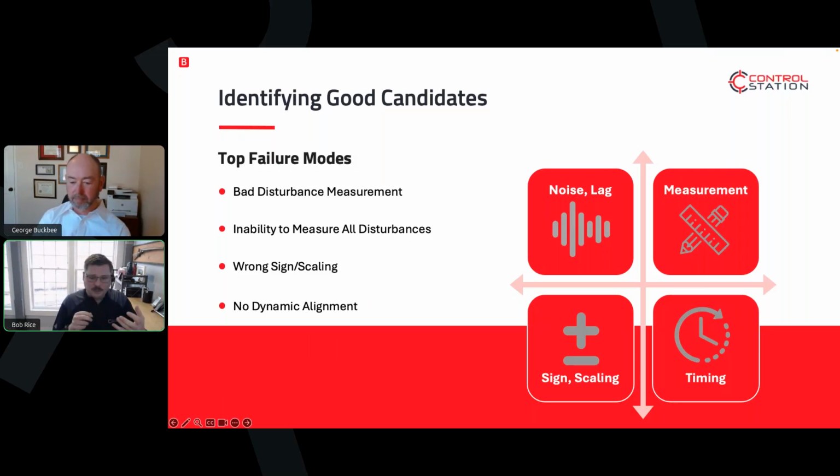You can measure flow, mass of material, moisture content, metal content, recyclable content. They measured all of those and fed that forward to the furnace and trimmed out the natural gas, basically saying, hey, I'm getting a wet slug of garbage into this system, so let's make sure that we are accounting for that. Those built up over time. They didn't start with all of them. They started adding additional disturbances as they found, hey, here's another major disturbance that can go on here.